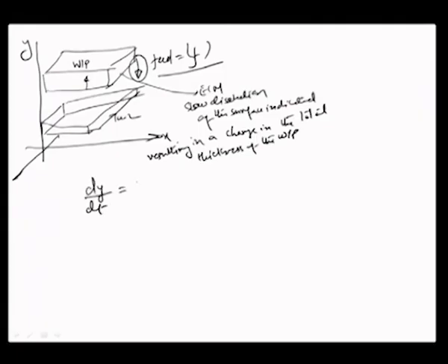And so we found that we can represent this whole kinematics by looking at the rate of change of y. y is the distance between the workpiece and the tool surface, and y is a function of t, because there is a continuous dissolution and feed of the workpiece towards the tool.